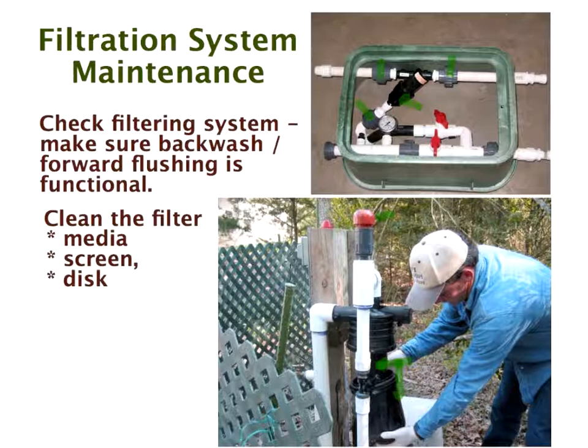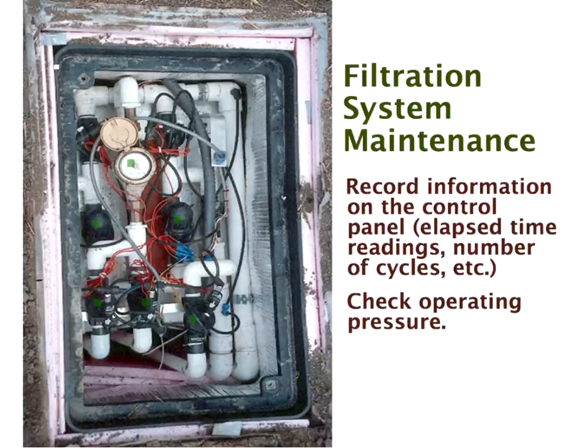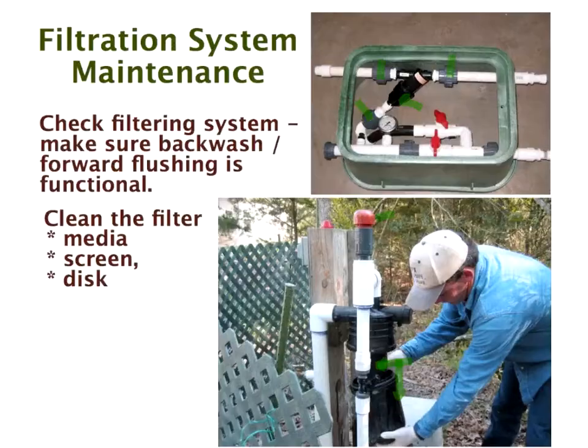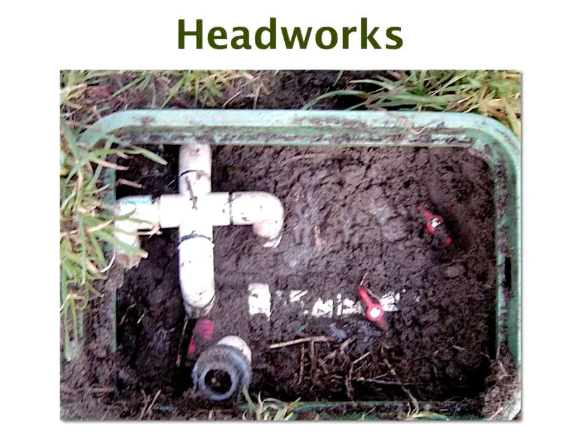You see, this headworks here doesn't have a bottom, and I think this one here before it also doesn't; you can't see it, but that one also doesn't have a bottom. Most of them don't have bottoms. And if you don't have a bottom, you need to put, I would say, 12 inches of gravel underneath the headworks to ensure that you don't get dirt being brought up from underneath, and you don't have gophers.